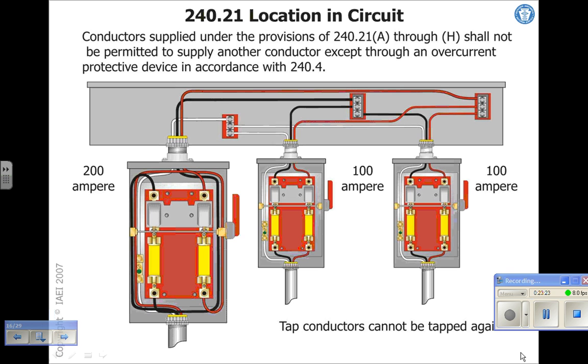So notice the 3 red circuits. These are all 3 single phase motor starters or disconnects, right? We have a black and a red feeding each one. We have the neutral here. If we were feeding this with single phase power, we would come into this auxiliary gutter and feed these 3 taps with power from the distribution panel. You'll notice there is no fuse between these hot taps and the fuse disconnect. Generally, they're fairly short. As a matter of fact, there's a rule about how short those have to be.